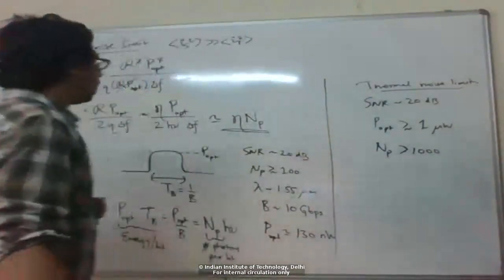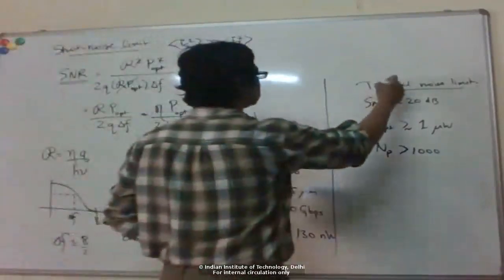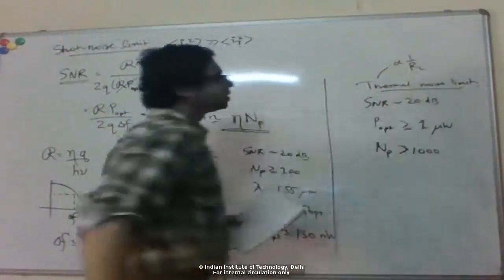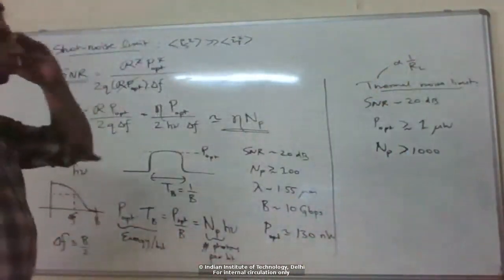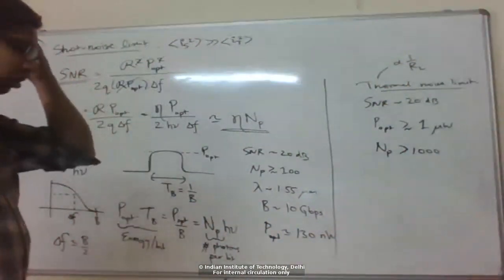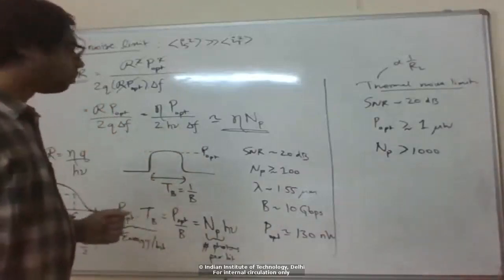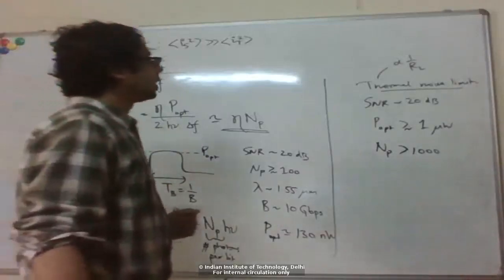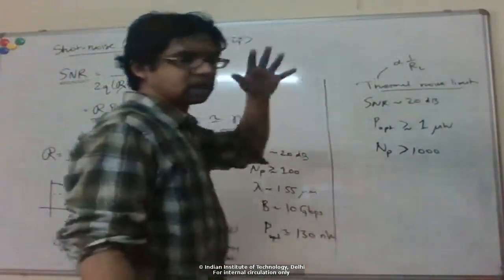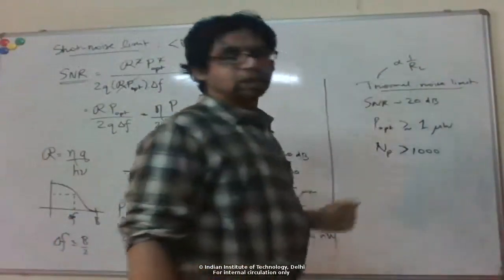Okay, unless in certain cases, for example, the thermal noise, recall this was inversely proportional to the load resistance. So if you use some very high load resistance to have very high gain, for example, that would limit your bandwidth of operation, of course. Right? When you use very large resistances, let's say tens or hundreds of kilo ohms, then the thermal noise goes down, right?